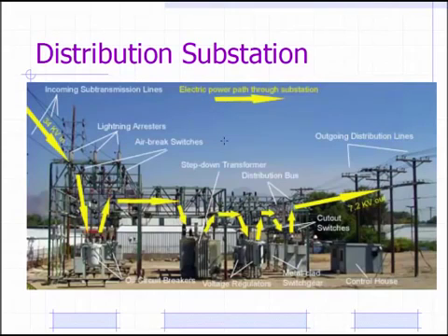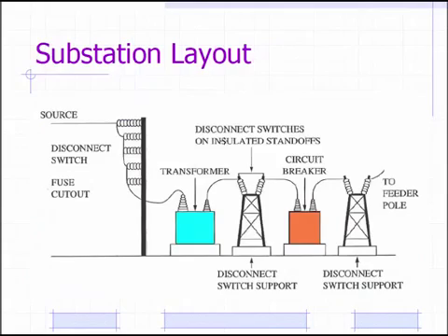And so substations really have two functions. They will typically change voltage and distribute power. That's their two things: change voltage, distribute power. And a kind of a third piece, they protect stuff, but it's kind of wrapped into the first. We've got to change voltage, distribute the power, and then we tend to protect those different distribution circuits. We tend to protect the equipment that's changing the voltage.